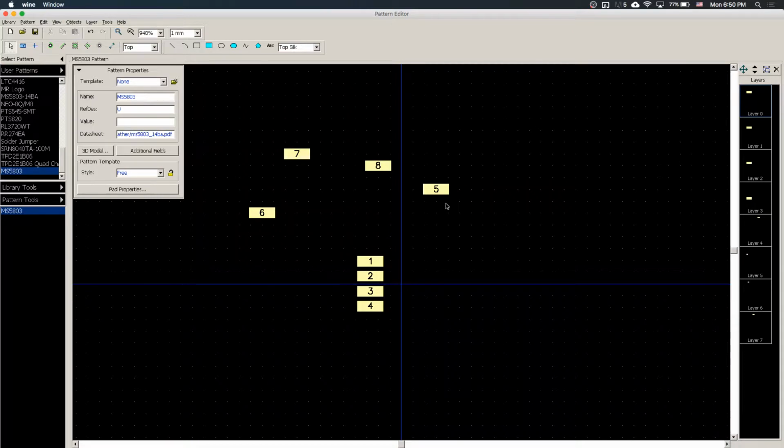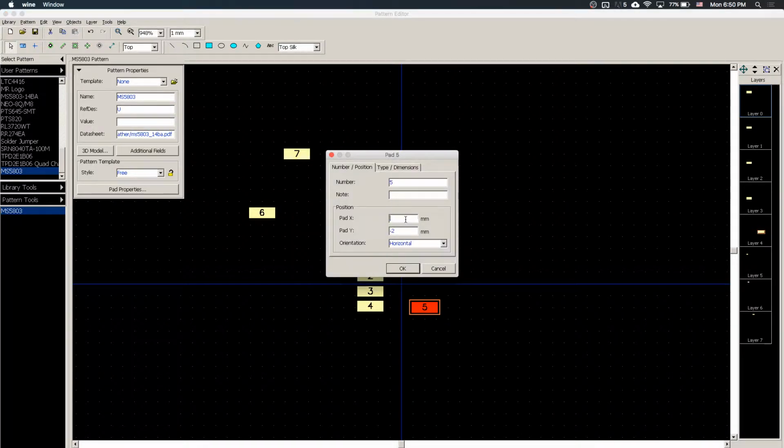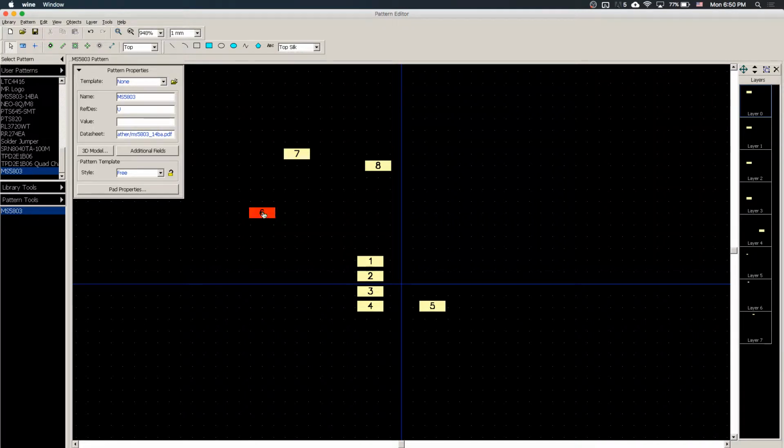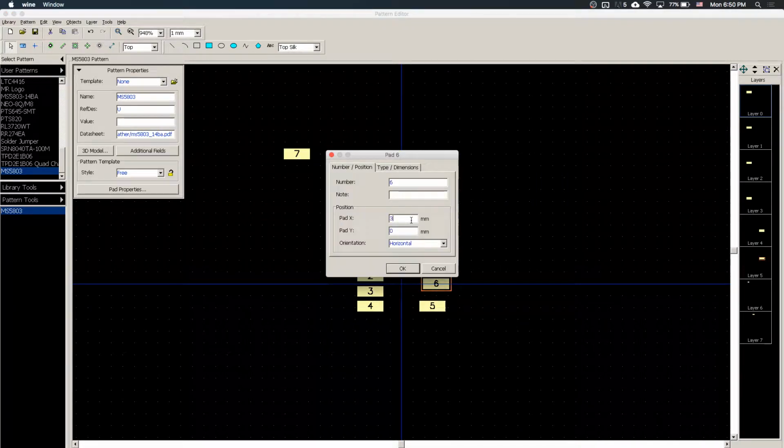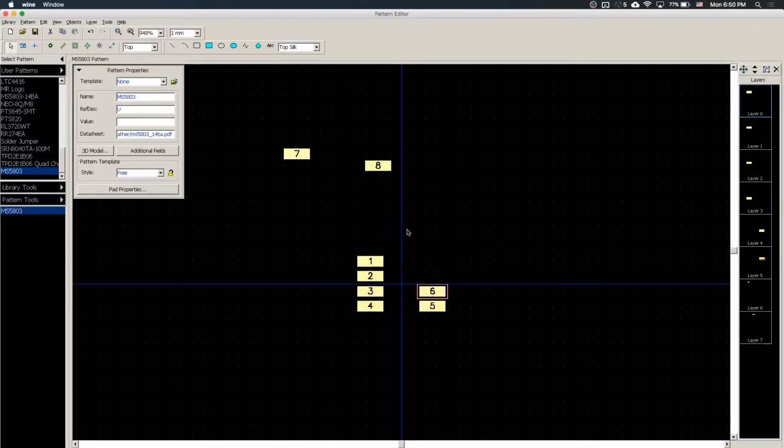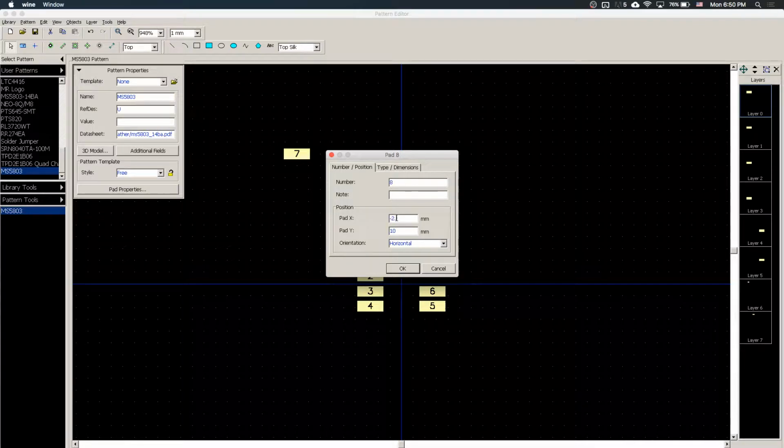The next step is to put in pin 5. As we mentioned before, we go in a U shape, counting counterclockwise. So pin 5 will be here, and just put in 2.675 and minus 1.9. Then pin 6 is 2.675 and 0.65, and pin 8 is 2.675 and 1.9.